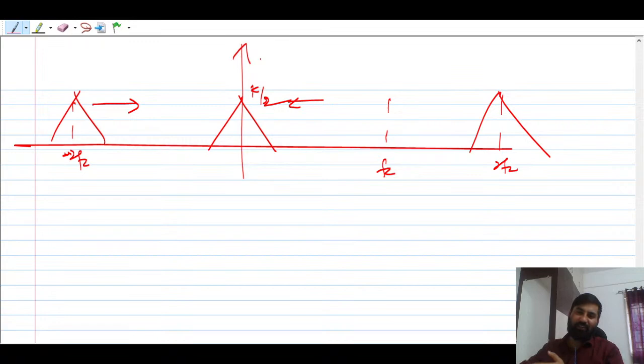As we discuss the types of modulation, you will find that suppose we are not happy with amplitude modulation, so we will go to double sideband suppressed carrier. Then if we are not happy with that, our goal is minimum bandwidth, minimum power. That can be achieved by only one modulation scheme, that is SSB. But in the case of SSB, it is restricted to telephone and such things.